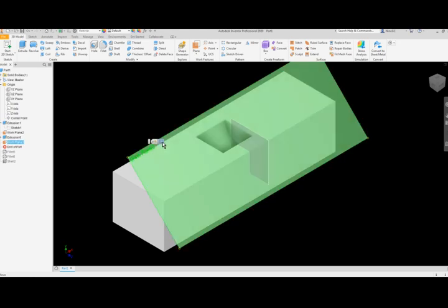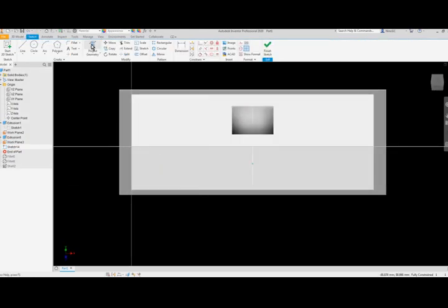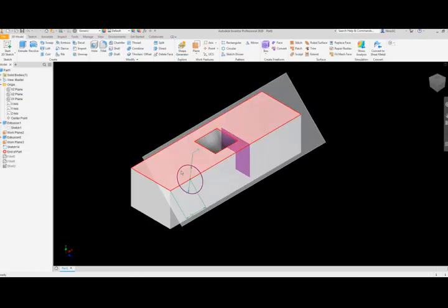On that work plane, I'm going to create a sketch. As always, I'm going to project that edge because that will allow me to create an anchor. I'm going to create a circle that is attached to that line. I will make that 16. I will make sure that it is actually attached, so if I try moving it, it will ride on that edge. That's fine. And that means that all I need to do is make one more dimensional addition. I will make that 15 also. Let's finish our sketch.